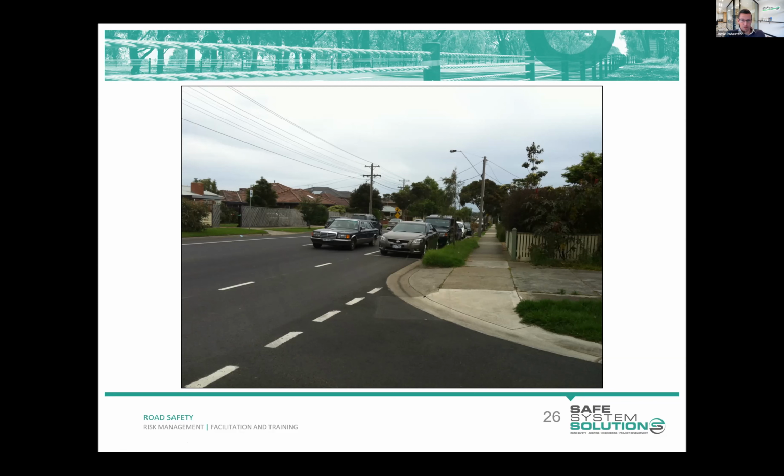Even if you do put in some signs to do that, that won't necessarily stop people parking in these areas. A better outcome would be to bring the hold line forward. As part of that, you might construct a curb outstand here to shelter the hold line that has been brought forward and vehicles waiting at that hold line. So that'd probably be the best situation.